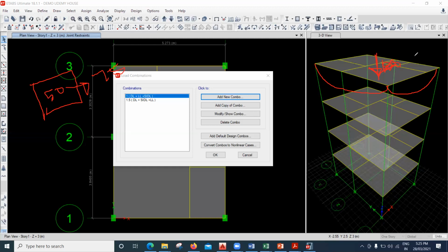Let us say 50 kg of a load is coming. This 50 kg of the load is going to come for sure. Once you put this building into use, 50 kg of the load is going to come for sure. And for this 50 kg, I have to make sure there is no deflection. So that is the reason here we are not multiplying this by 1.5, we're taking it directly 50. So this is called as limit state of serviceability and limit state of collapse. I'll delete this. So with this understanding, these are the two load combinations I've created, and I'll say okay to this.